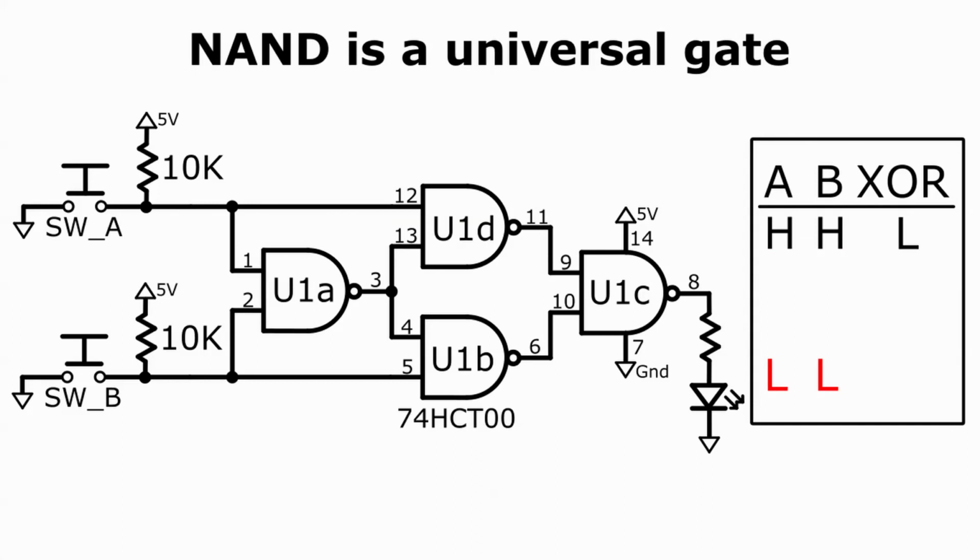In the last row of the table, both inputs are low. Let's jump ahead to gate D for dog. Since one of its inputs is low, its output will be high. We don't even have to look at gate A to see what it's doing. One low input is enough to force the output of gate D for dog high. Similarly, the one low output of gate B for Bob will ensure that its output too is high. That means both inputs of gate C are high and that its output will be low. I'll enter this into the truth table.